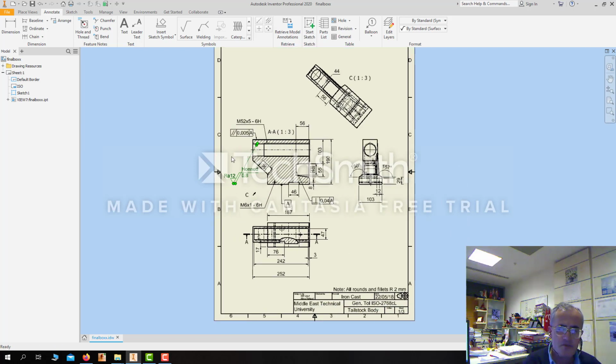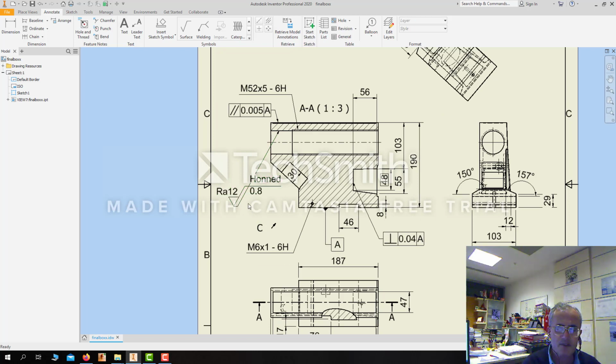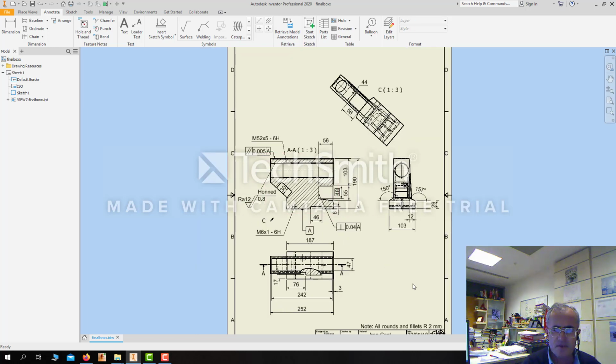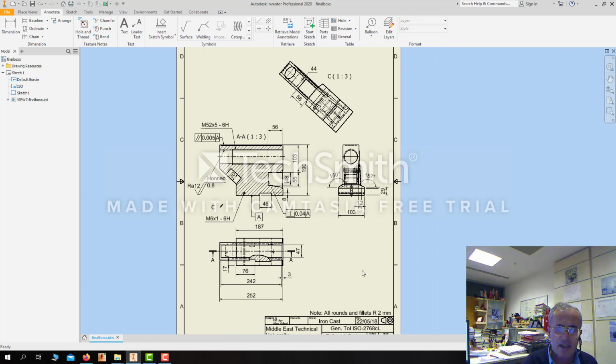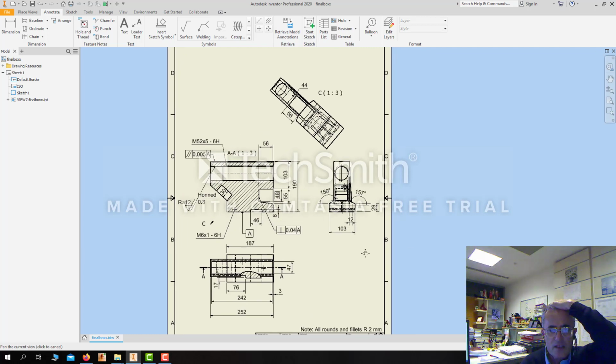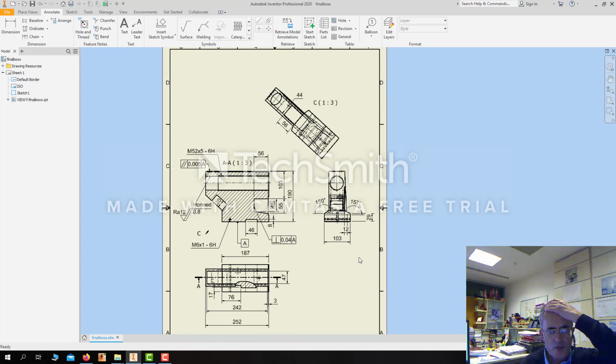Well, for this surface, that is the specified roughness value. How about the other surfaces? In this example, assume that except this one, for all the other surfaces, the roughness value may be the same. Instead of indicating each surface one by one and writing the same roughness value again, in the old version of the standard, there is a place for the note. At the upper right corner, we show the roughness symbol like this.